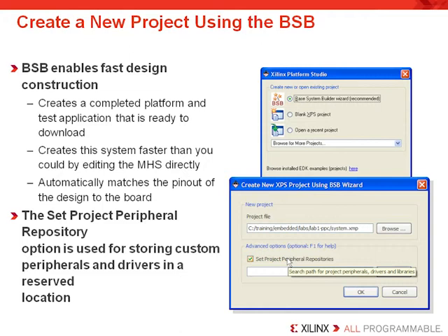When you select to create a new project and design using the Base System Builder, you'll be asked a series of questions about the project, such as what demo board, what processor, how do you want to configure the processor, what I/O interfaces are you going to use, what peripherals do you need, etc. Now this is possible because of course the board has already been made, so if there is an SDRAM on the board, it makes sense to make it easy for a customer to add an SDRAM controller onto the PLB bus, right? Right. Now, after you've answered all the questions, your MHS file will be made for you.